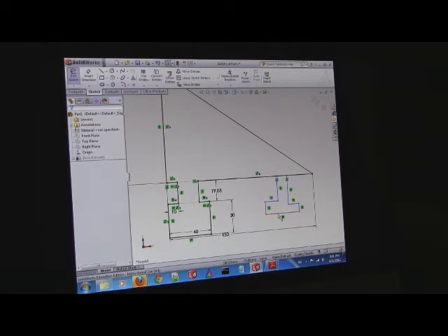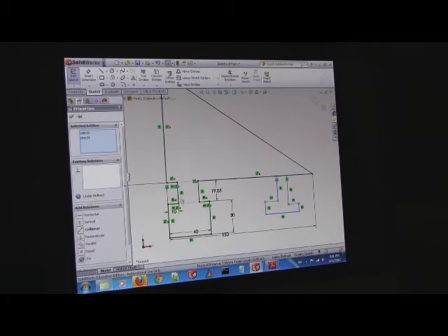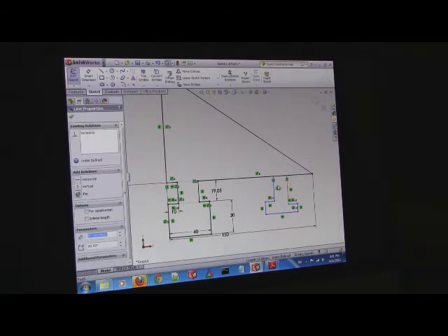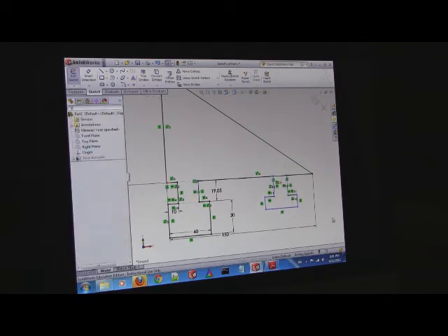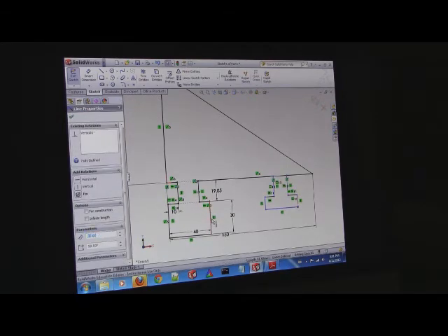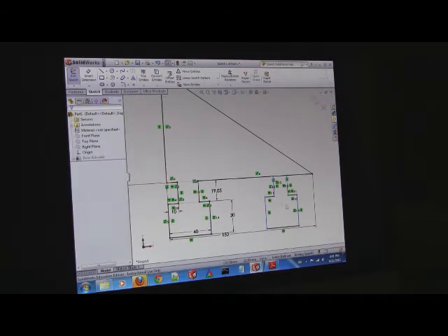So watch this. I click this line, and the one with the 10 on it, and I press equal. I select this line, and the one with 19.05, and I press equal. Then I press this line and the 30 millimeter one, and I press equal. And the final thing I'm going to do, so let's just stop there for a sec. Did everyone do that? And do you see why I'm doing this? Yes. And in the end, we will do that.